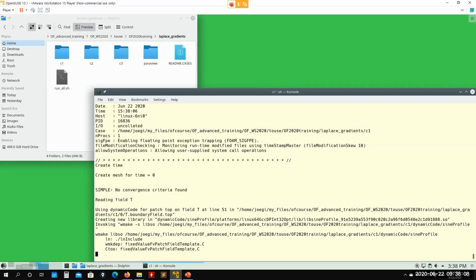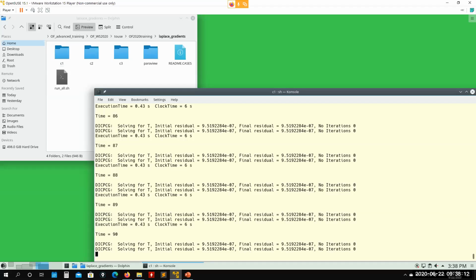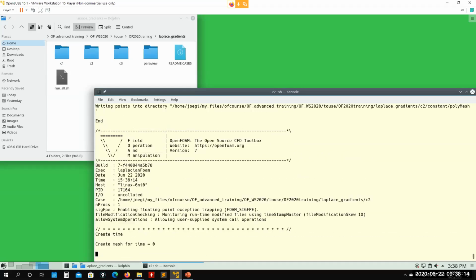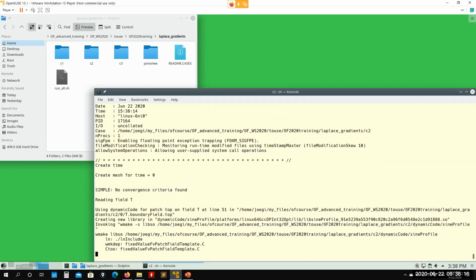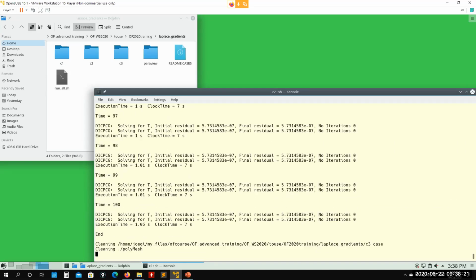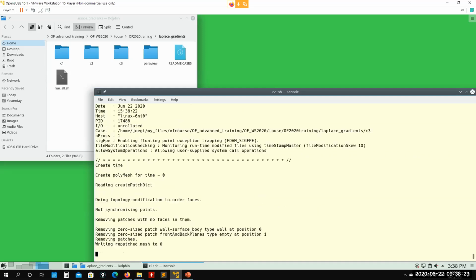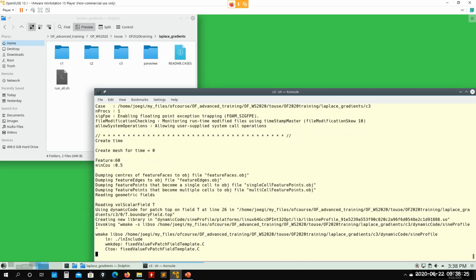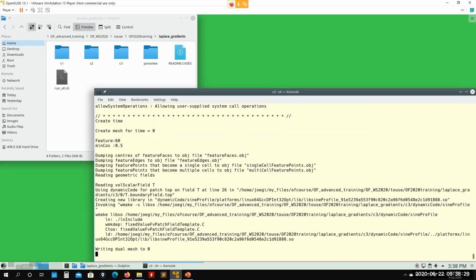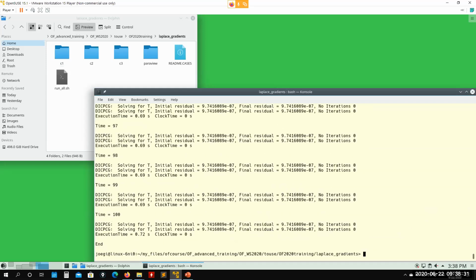So we'll run 3 meshes: quads, triangles, and polyhedral cells. We are going to get exactly the same solution, but when we look at the gradients, what is behind doors, we're going to see that the gradients are approximated in a different way. And in some cases, those gradients will be responsible for making your solution diverge. And we're going to see that here, okay?